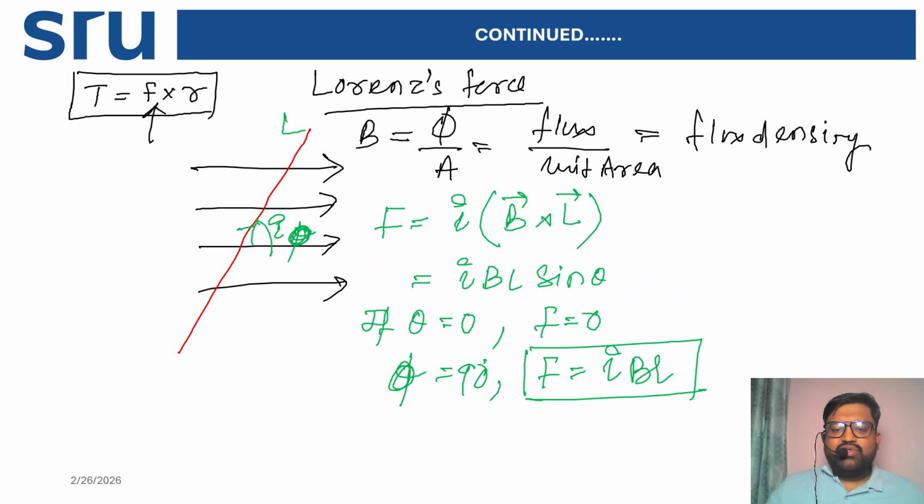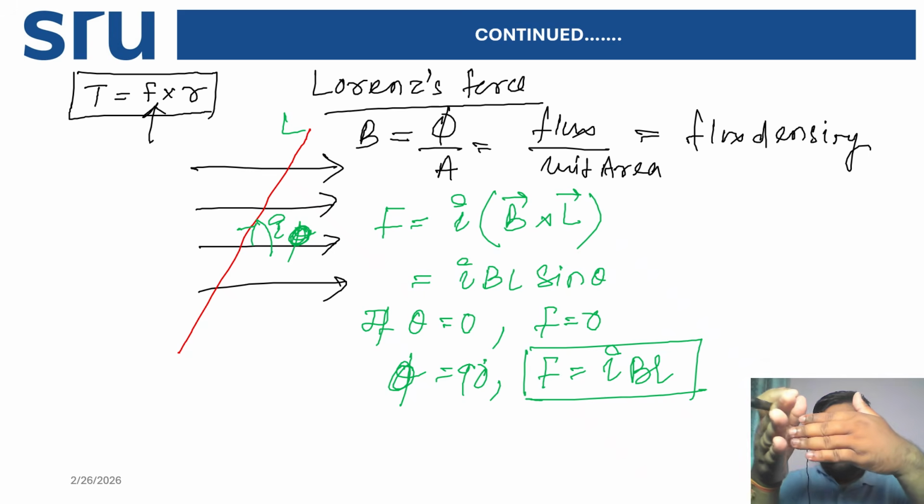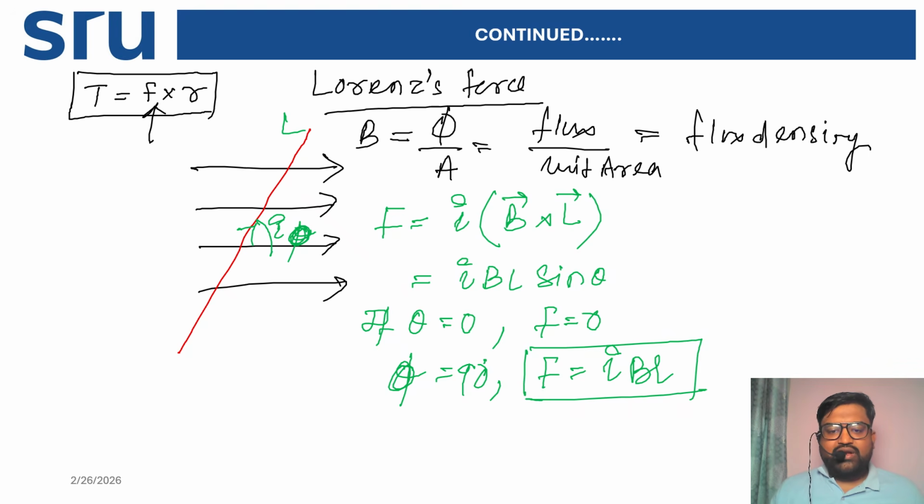And if you see the practical condition also, if your magnetic flux is going from left to right, and you are putting a current carrying conductor in a perpendicular manner, then when it passes, it will cut all the conductor points. That's why you are getting the maximum force. You can put here F maximum. Okay, this is nothing but the force we derived.